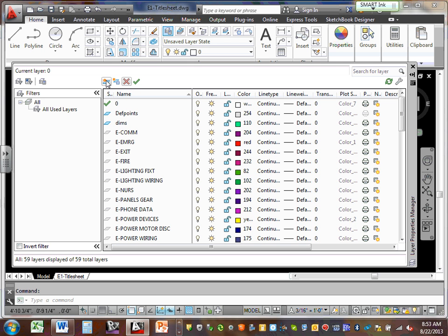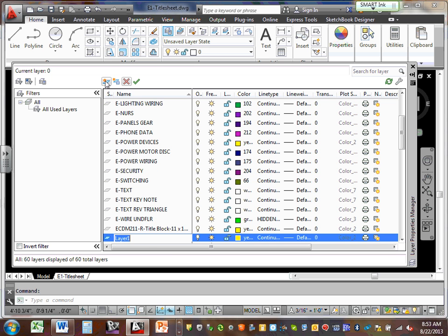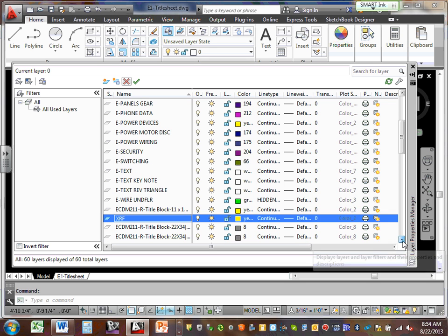Let's start a new layer. Really, that's what I want to do actually. Can you click on here? Can you see that little icon here, everybody? Right in here, create a new layer. For this layer, guys, I would like you to type xref. This layer will be assigned to every single thing that you bring in as an xref. Every single thing that you xref. Okay, so now I call it xref.